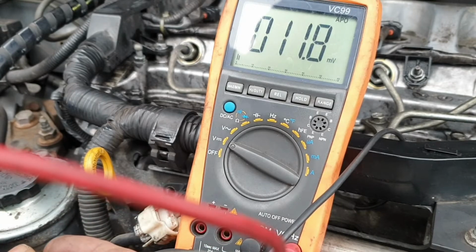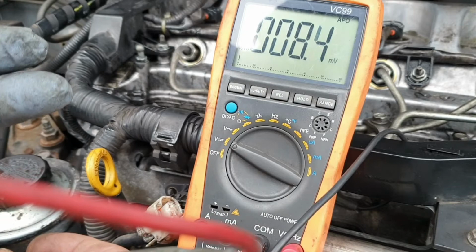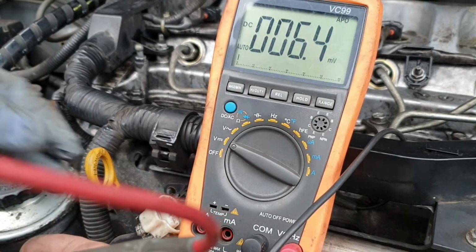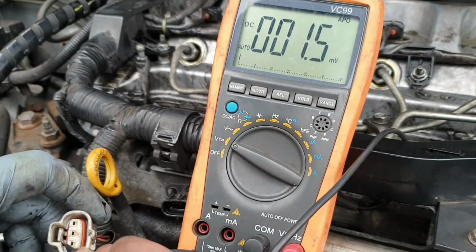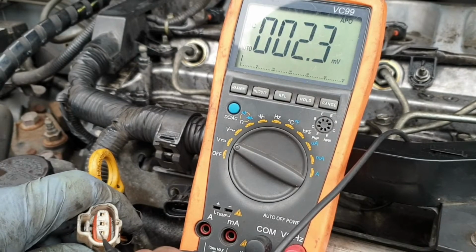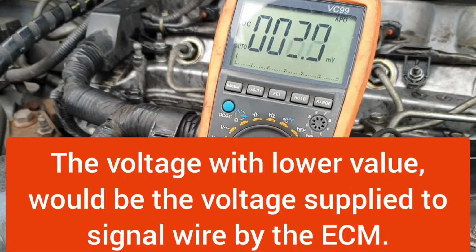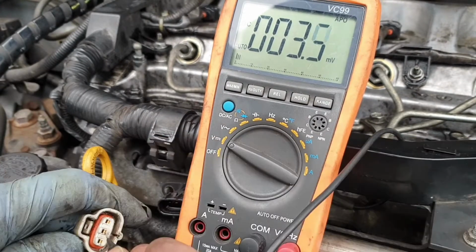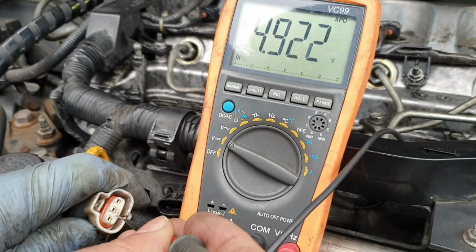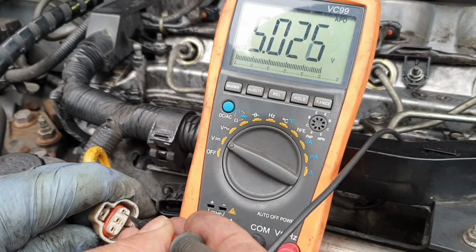It does not apply for all cases, but in most cases, if you measure with the connector disconnected from the sensor, the value would be the supply voltage for the signal, which is here, the middle pin, 4.9, and this is exactly 5 volts.